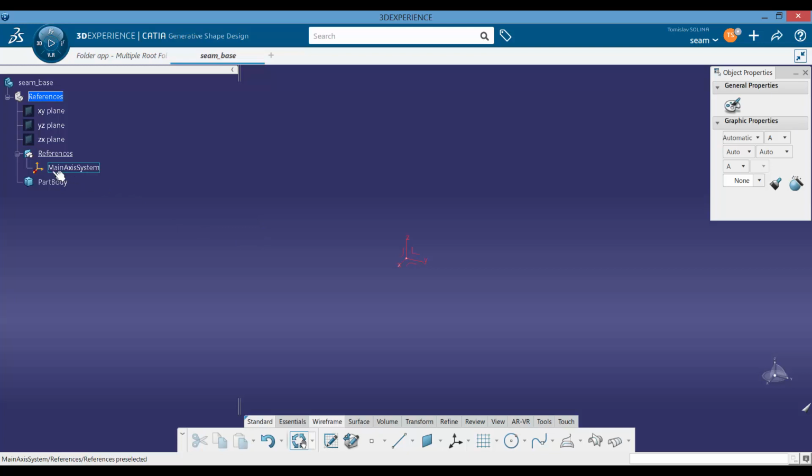In this case, we have this main axis system that we created, and we said we will use B-rep here, because in this case this is not an issue, as this is a static element which is already isolated. It won't get modified, so its references will always stay the same. So if you select this plane here, we are always going to know that this element was selected. If we were using the outer one, which is not isolated, it could happen that when we are transforming this into the new part, the part will lose references.